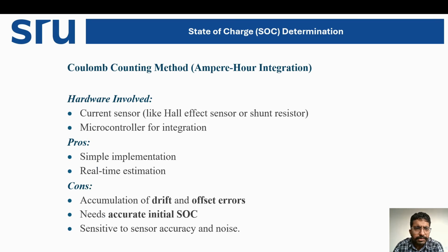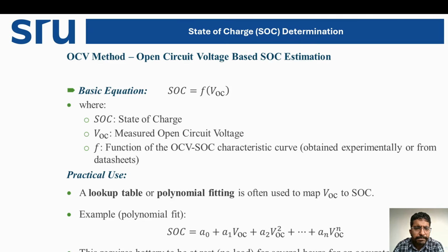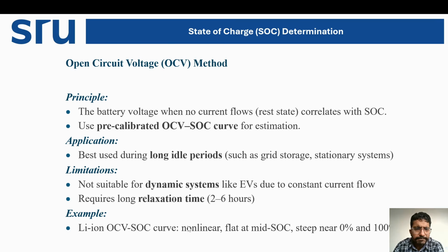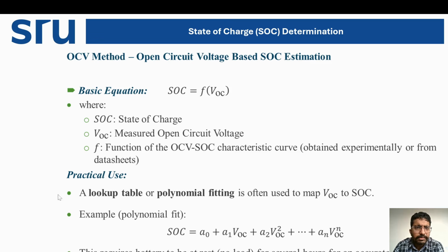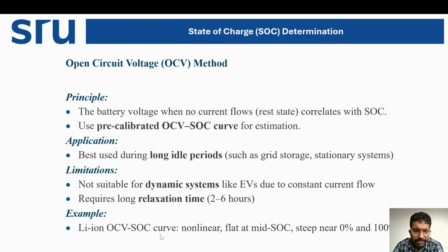Now coming to the further explanation of open circuit voltage based state of charge estimation. How is it done? We apply a simple polynomial-based curve fitting. As already mentioned, the curve is somewhat non-linear, not a linear x-axis and y-axis relationship.